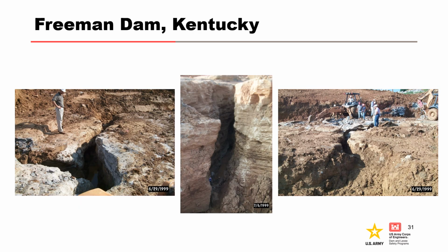The dam was breached and the foundation was exposed, which revealed solution features present beneath the embankment. Clearly, the infilled soil in the solution features had eroded over time, providing an open conduit for seepage to carry off the core material. It was noted that no dam or foundation soils were ever observed on the surface or downstream of the dam. Foundation conditions revealed in excavations led to a decision to completely remove and rebuild the dam with proper cutoffs, rock treatment, and filters.